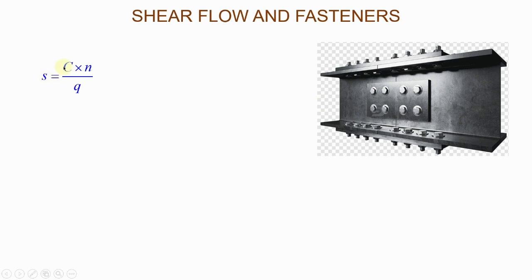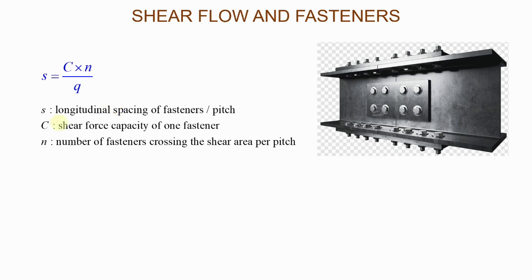So S is equal to capital C multiplied by N and divided by Q. And so in this equation, S is the longitudinal spacing of fasteners. And in most of your questions, they may refer to that as the pitch, okay? So what do I mean by the longitudinal spacing of fasteners? Okay, so if you look at the picture here,